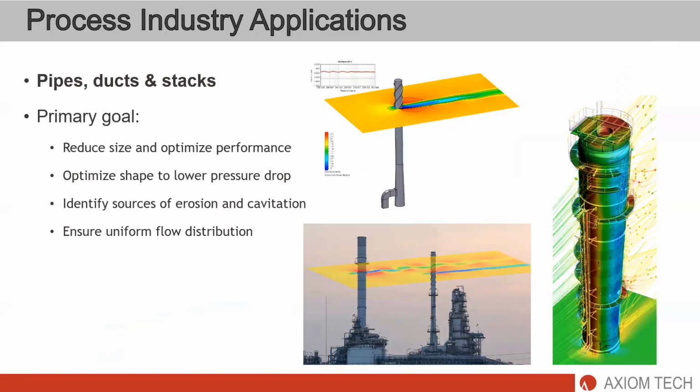The next of the process industry application is connected with pipes, ducts, and stacks. You can reduce size and optimize performance, determine pipe losses and flow resistance, optimize shape, optimize use of baffles, design out cavitation, optimize mixing, and for example, minimize power requirements.